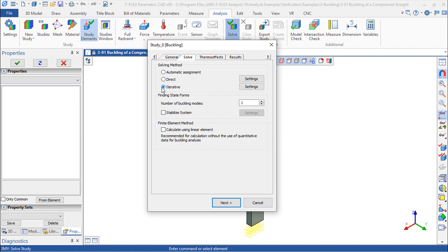For last, this iterative method, so the system of equations is solved by these methods, and these do not require the complete inversion of the matrix, and this requires less RAM, so the calculation will be smaller and proportional to the number of natural vibration modes that we define on the calculation. These modes are inserted here. In our particular example, I have only one mode, but I can increase this value and create other modes for the calculation.